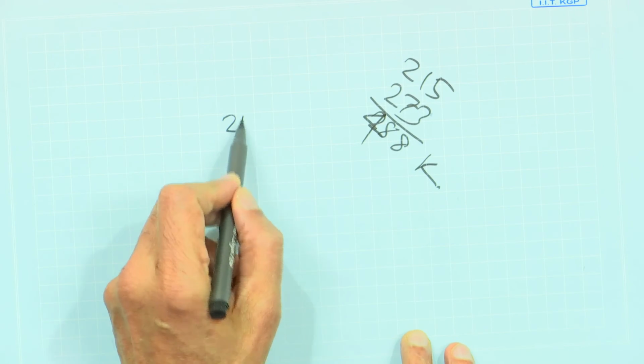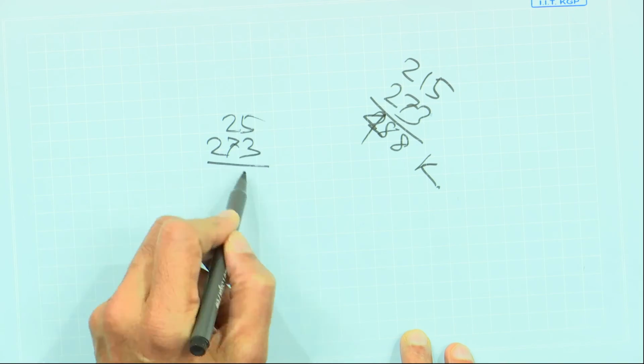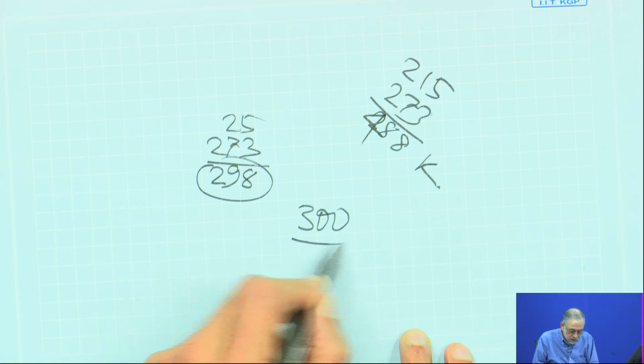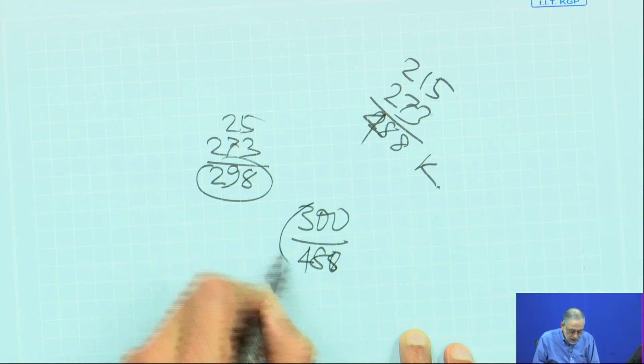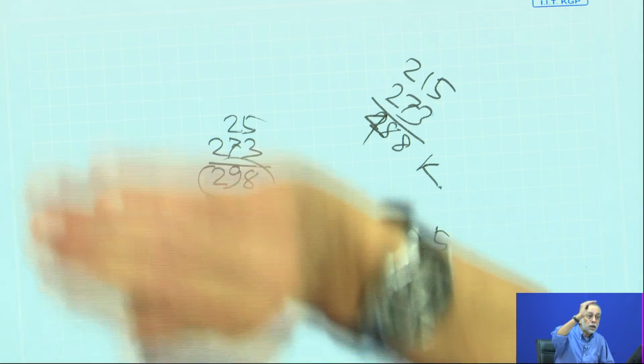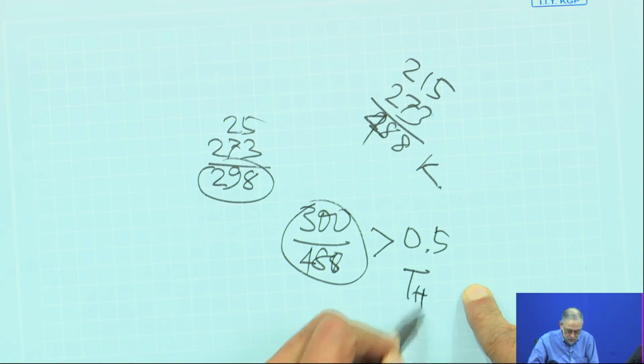Room temperature, which is 25 degrees C, in Kelvin is about 300, right? So what's the ratio? 300 divided by 488 is well above 0.5. Do you agree? That ratio is called homologous temperature. T sub H is shorthand for homologous temperature. Anytime you're above 0.5 homologous temperature, metals start to creep. In solder, even at room temperature, let alone at high operating temperatures, you're way above the 0.5 critical threshold. So any stress in solder is going to cause a lot of creep deformation.